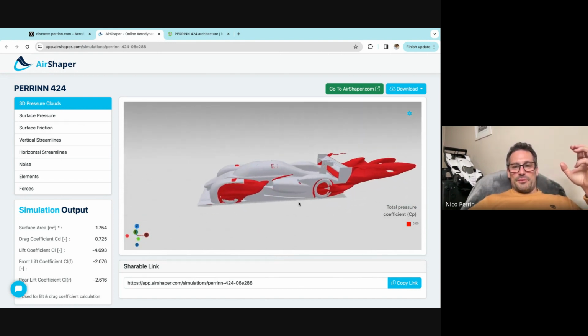The drag is always coming from the back of the car because that's where the most separated air happens. So think of the car as a wing, and if you want to increase your drag and downforce point, basically you start increasing your rear wing and your diffuser expansion.